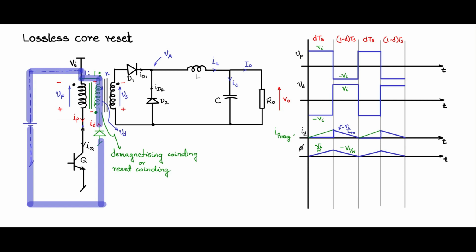The reason is that if there is a leakage here, that portion is not covered for mutual inductance for demagnetizing. So that can cause a large spike across the device when it is switching off. That can also be avoided by having a snubber circuit, which I will discuss later when I am discussing devices.